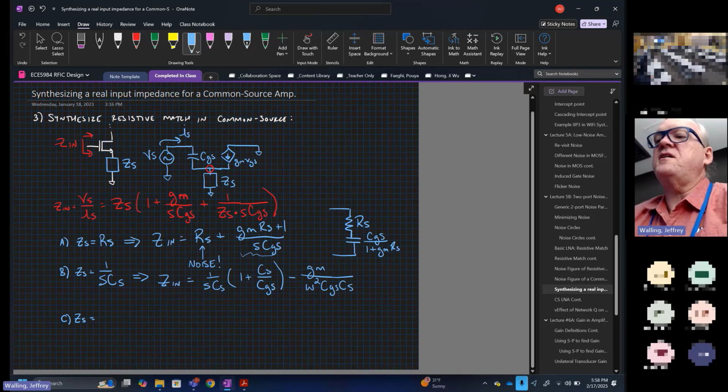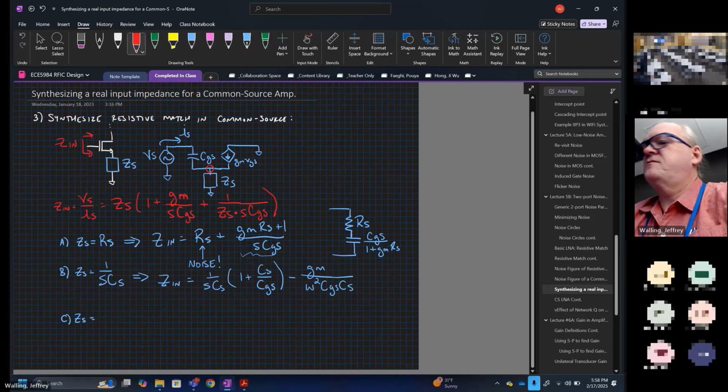All right. Anybody, what's wrong with this circuit? There's something glaringly wrong with it. It's still capacitive, so we didn't really fix that portion. But even more importantly, what does this sign mean? It's a negative real impedance, right?